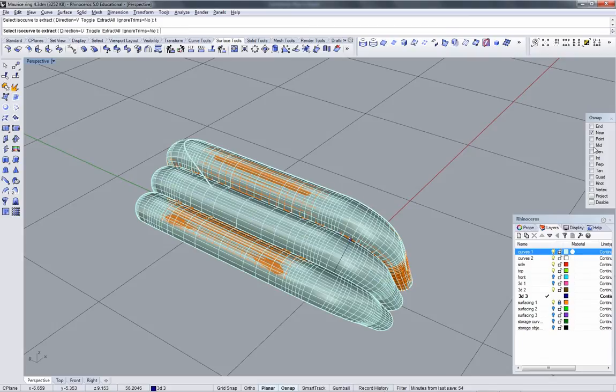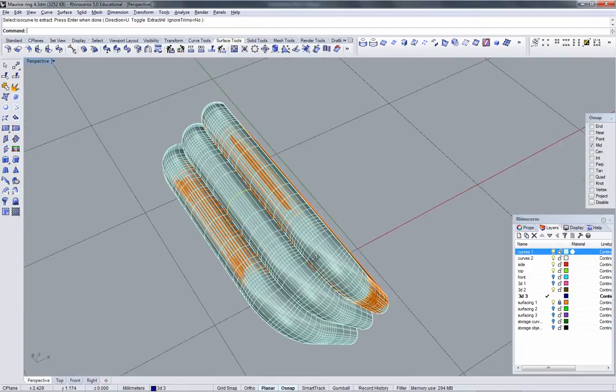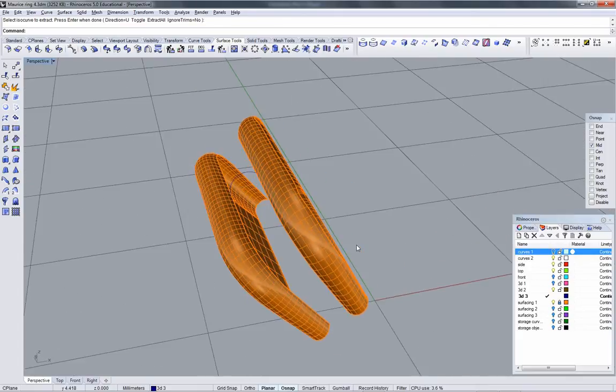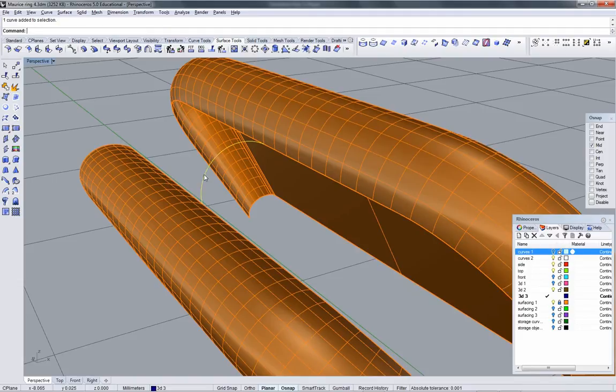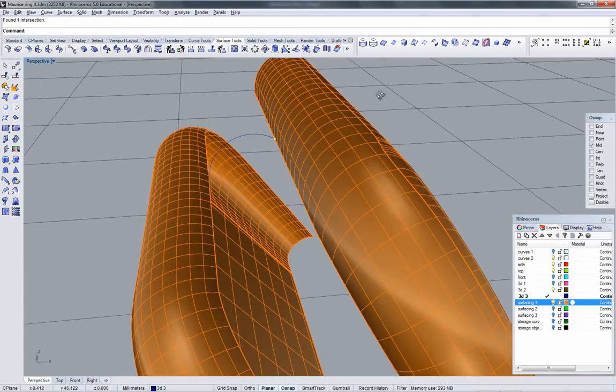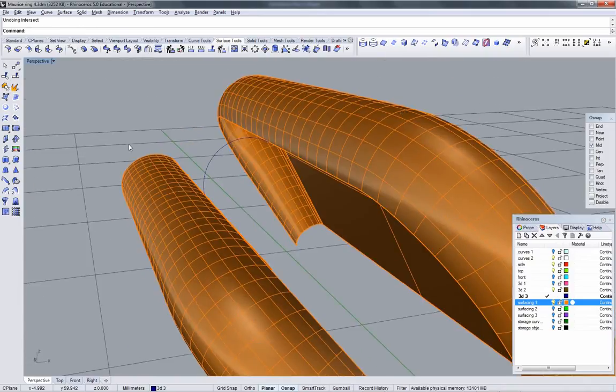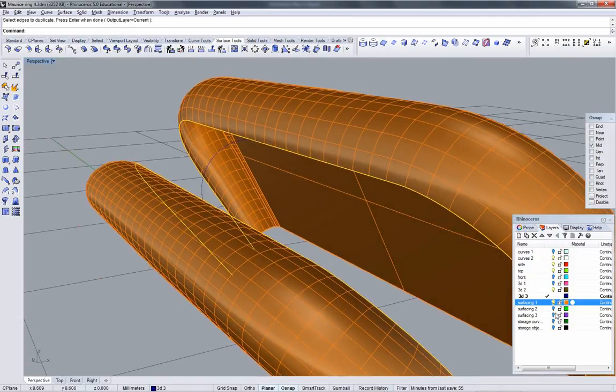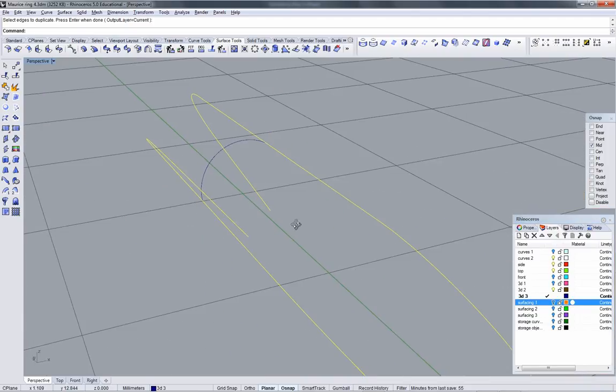Toggle, mid. Okay. Turn that off. See if that's valid at all. Grab this intersect. Yes. Actually, I don't want to trust that. That's surface to surface. Surface to curve. I'm going to duplicate the edge, because the edge of these two are going to be my rails no matter what. So might as well get that over with.